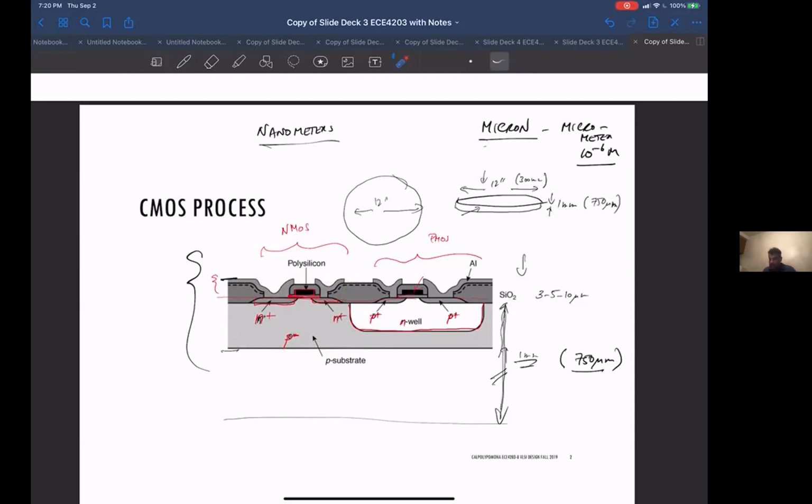Now, because you also need PMOS transistors in there, you've got a problem because the PMOS substrate is n-type. So what they do is they build so-called wells in this p minus material. They implant donors in this so-called well. So they change the substrate for the PMOSFETs to be n-type by creating this area of n-type on top of this layer. And then you put your P plus contacts on the surface.